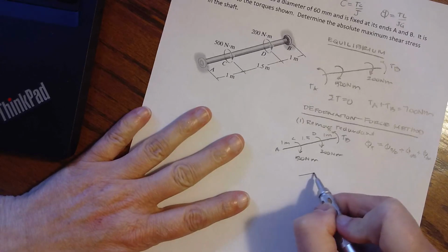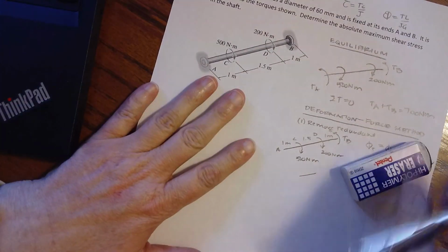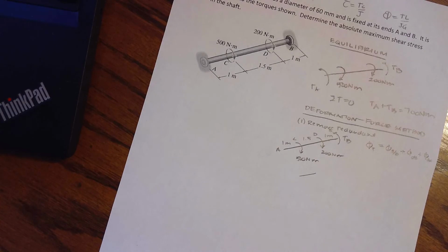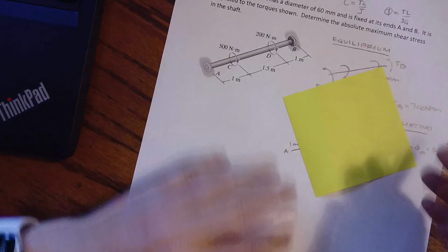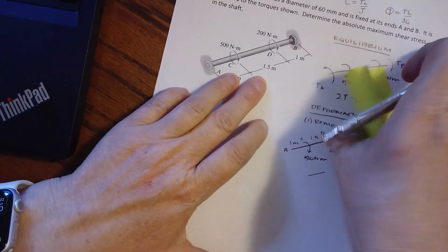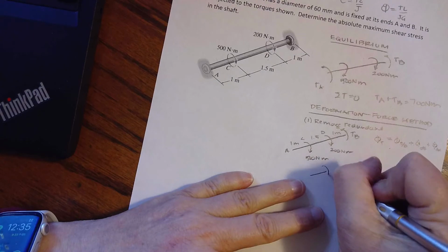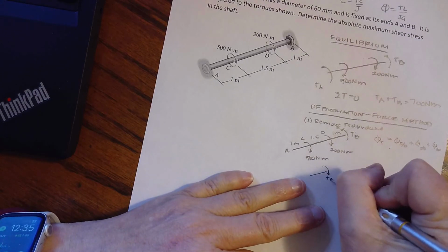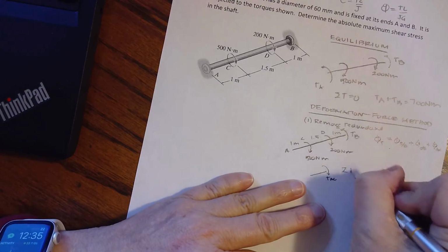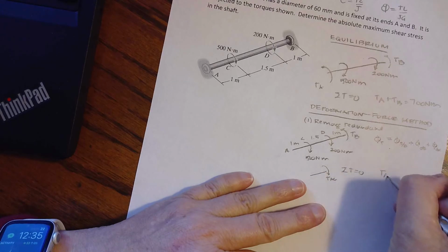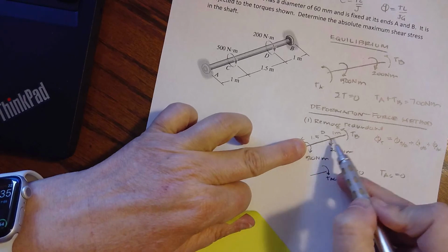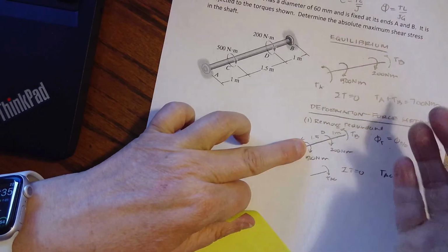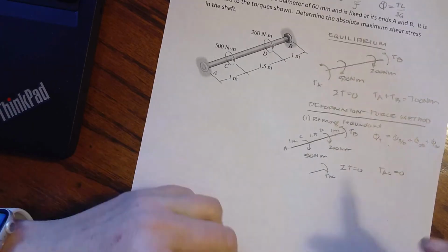If I look at A, and I take my handy dandy Post-it note, we work our way backwards. I can see that there's no applied torque. So if I have no applied torque, and I'm looking at the torque from A to C and I sum those torques equals 0, the torque from A to C equals 0. It's going to be rotating here at the end because we have torques in these other segments that are rotating. It's just going along for the ride.